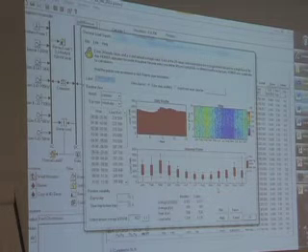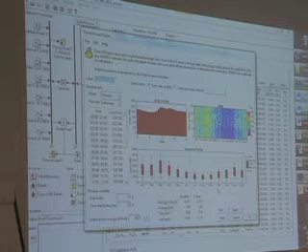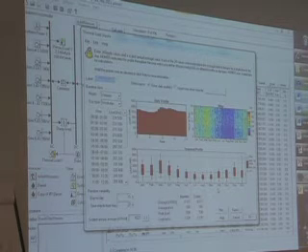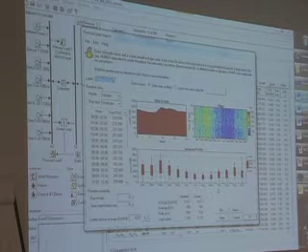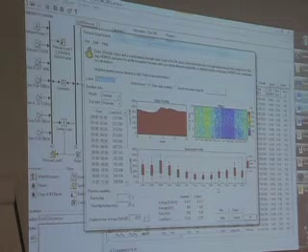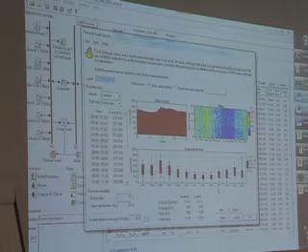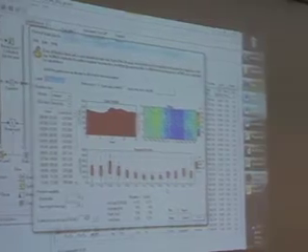The local site data was not especially helpful, so on this preliminary one, it was taking the annual use of heating fuel, or the fuel that we thought was allocated to heating, and then looking at the heating degree days on a 30-year average, and allocating that annual amount of fuel across the community based upon those heating degree profiles.